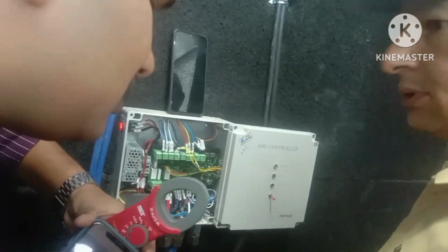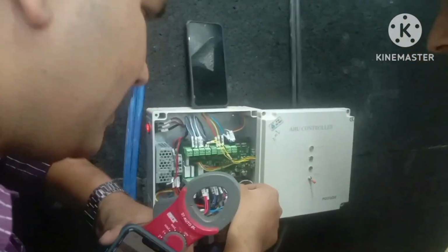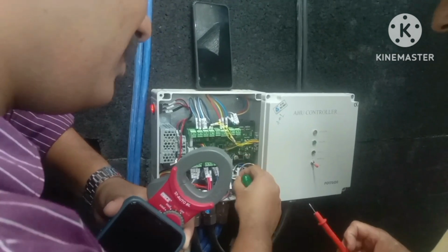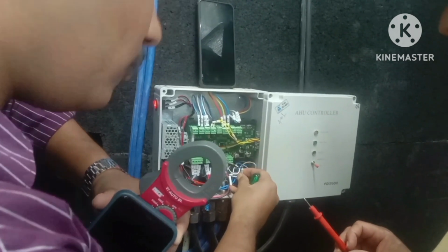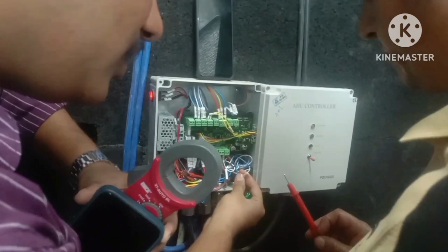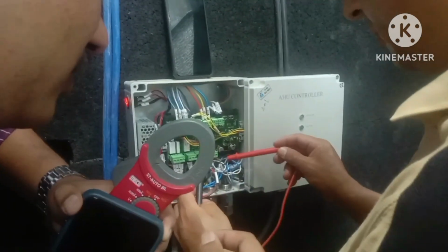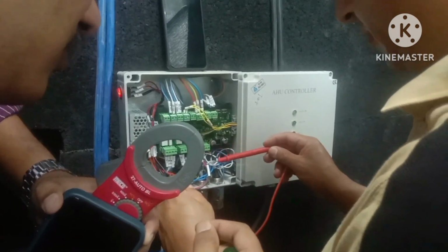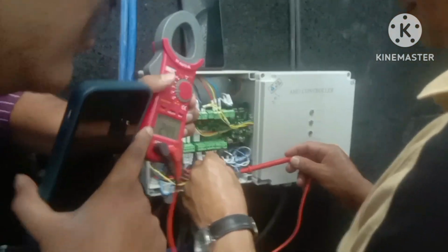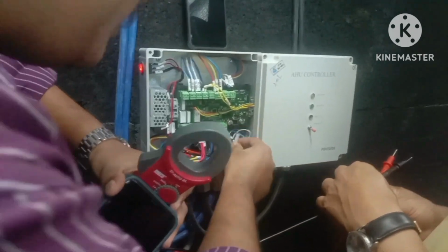So sometimes this condition can also arise, that our SMPS is working. So even if you get 24 volt here or if you don't get 24 volt, just loosen the wire. See whether it is properly crimped or not. After testing here, just remove both wires and connect directly to the multimeter. Sometimes if there is not proper crimping, then you will also not get 24 volt here.